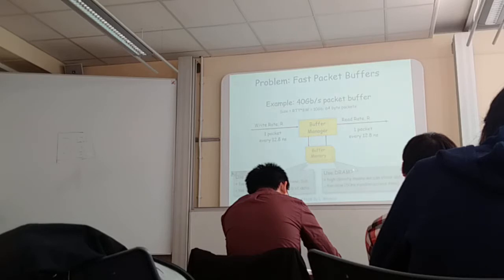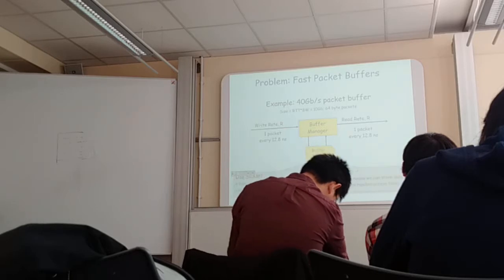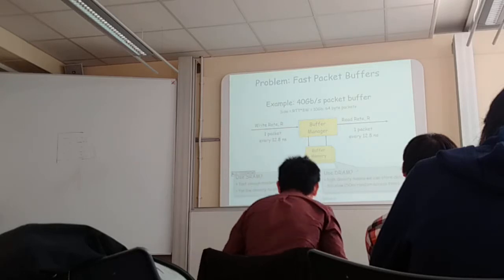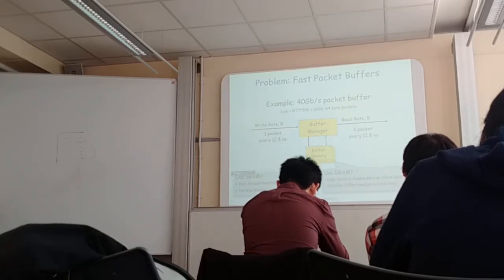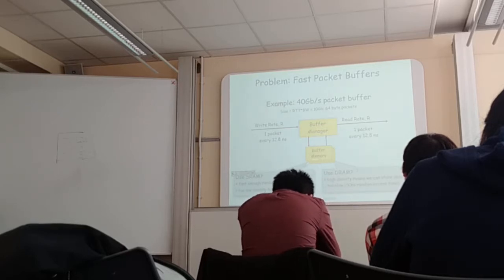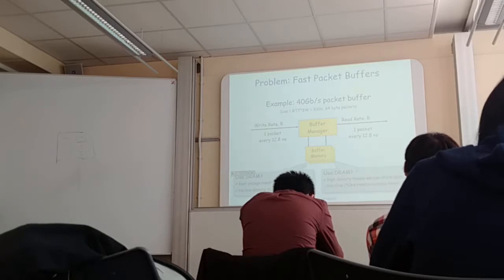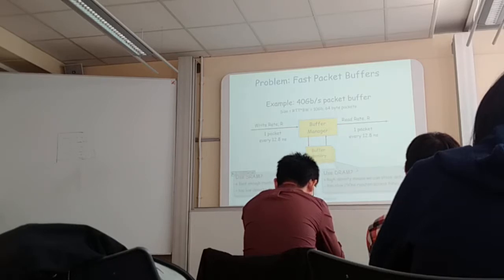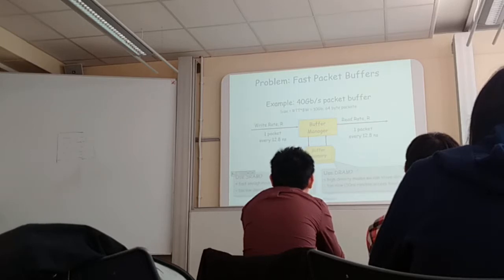Usually people maintain smart data structures for packets, whereby they store the header in an SRAM and maybe the packet data in a DRAM. There are lots of schemes like that. But here the message for you is to understand that buffer memory is very critical, and it's important what to pick to have there. For example, even if you pick an SRAM and assuming that this memory is available in an SRAM size-wise, power consumption is a big deal because SRAM consumes much more power than DRAM. So the question of memory sizing in a router is extremely important.